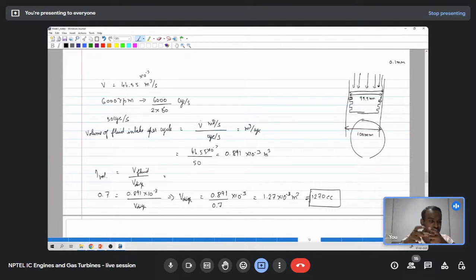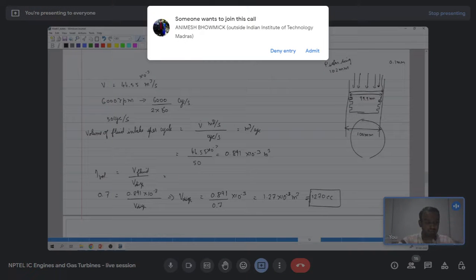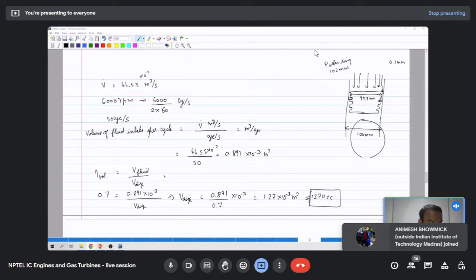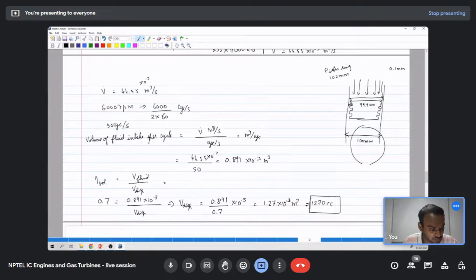At a free state, for a cylinder of say 100 mm diameter, the piston ring will be like 102 mm. So we have to compress it by 2 mm and then insert it into the cylinder. So there will be a constant force applied outward by the piston ring, which will prevent the fluid from leaking through the piston.